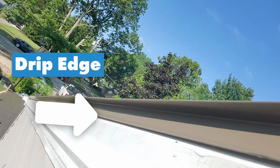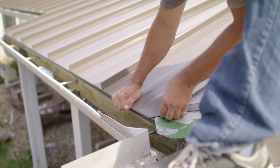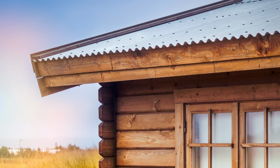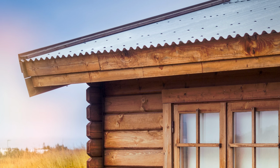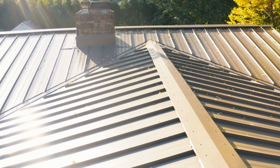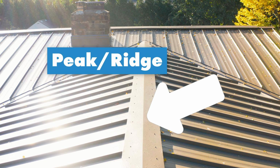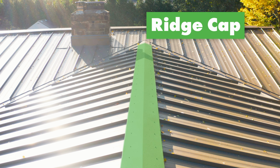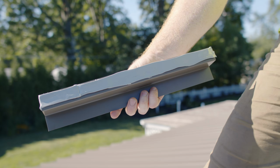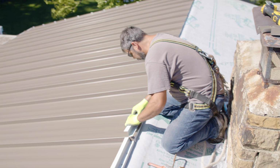A standing seam metal roof employs bends in each panel to hook onto the eave. An exposed fastener roof is installed with each panel overhanging the eave with a molded foam closure to stop up any gaps. The top of the roof, where the two planes meet, is called the peak or the ridge. The metal trim that covers the peak is a ridge cap. An exposed fastener system again uses molded foam closures to fill in the gaps between the panels and the ridge cap, while a standing seam system uses a bent piece of trim called a Z closure to connect the panels to the ridge cap.